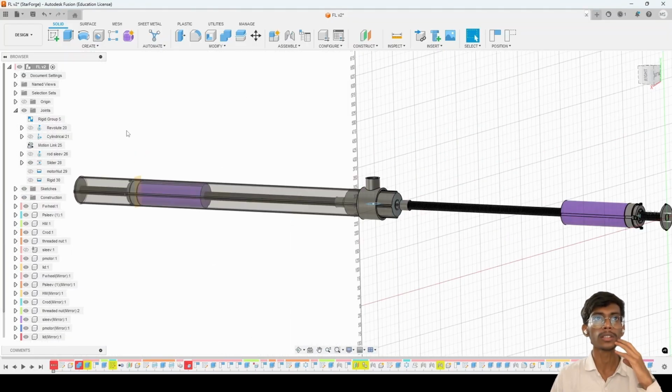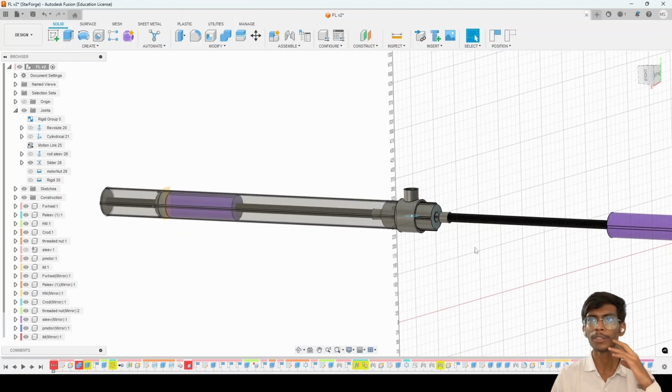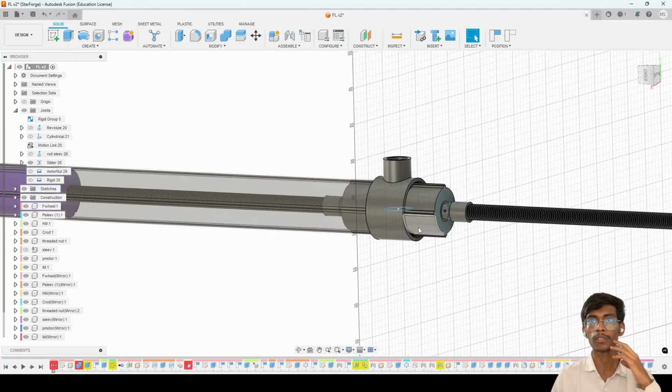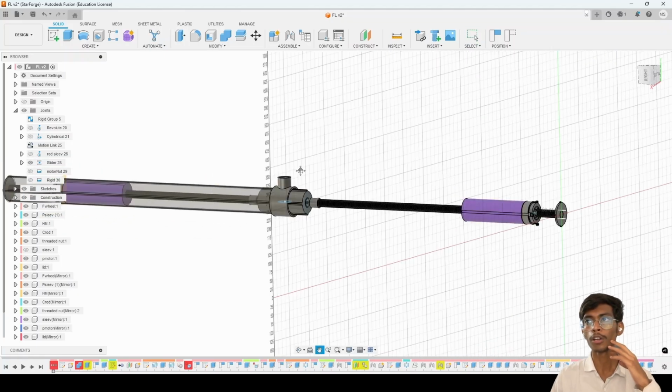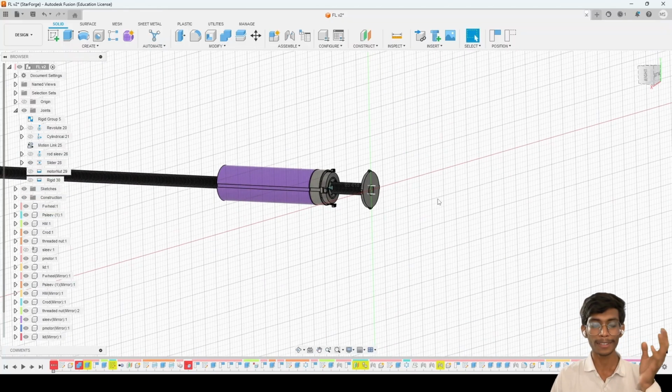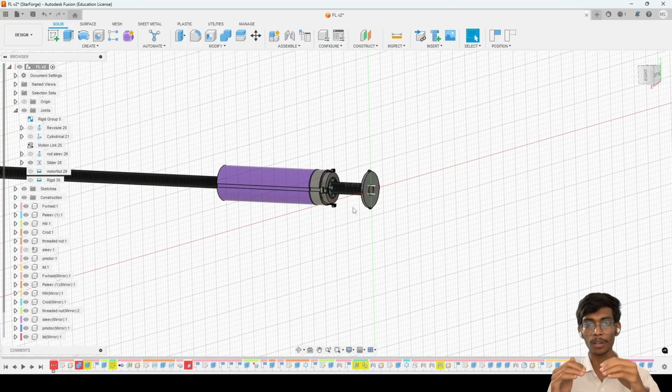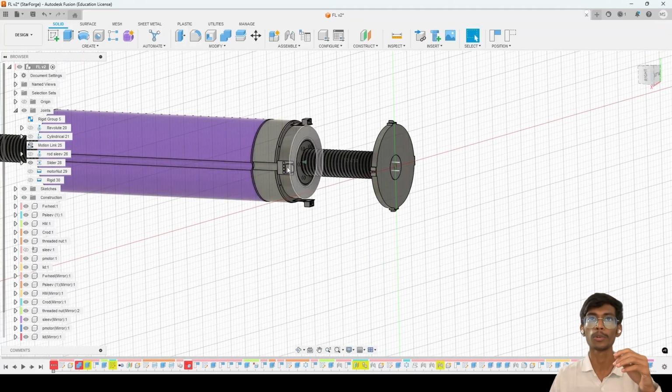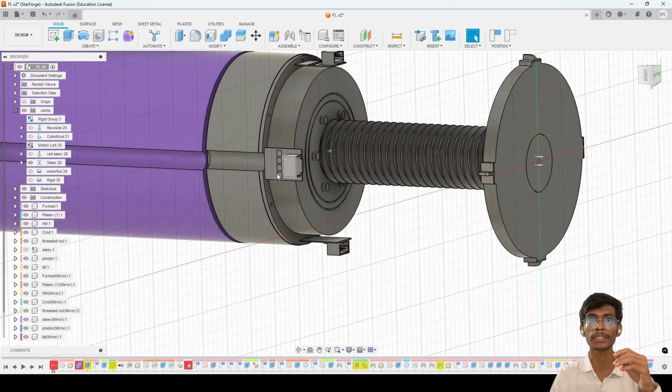After this, you can see this is just the mirror of this. This is the way from where the power and all the cabling is going to be done. The power delivery to the hollow motor would be something like using brushes, the brushes we use in brushed DC motors. They are dynamic contact points, moving contact points for transferring electricity.